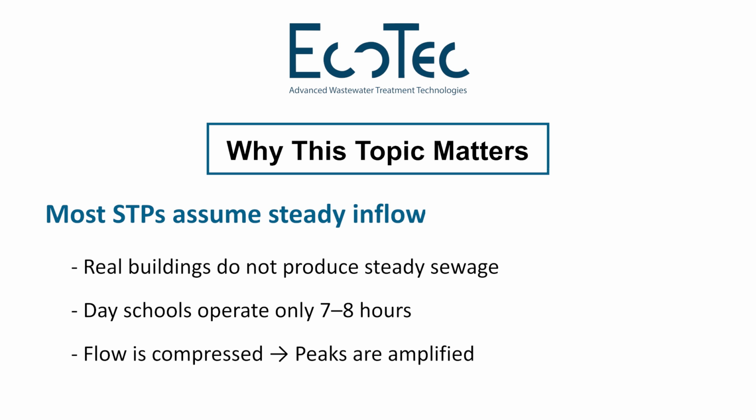One significant factor in a school is that the peaks are very high because the students are rushing to the toilets and the urinals during the time when they are free from class. This has to be also considered in designing the sewage treatment plant collection tank.